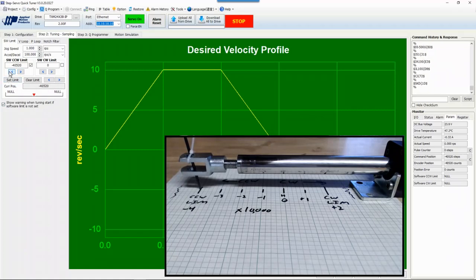That looks perfect. So now that our counterclockwise limit is set, and you can see it's -4520. So it's just a little bit further than right dead on the 4-inch mark, which is exactly what we want. We want a little bit of overshoot allowed. Because remember, this is a software limit. We're saying that our mechanical hard stop is this line over here. So there's plenty of buffer here between the counterclockwise limit and the mechanical hard stop.